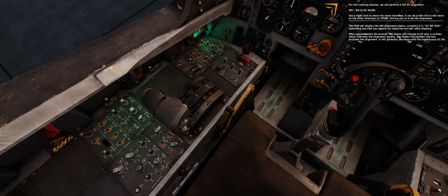To ease the numeric inputs, you may want to bind the numeric keypad of the UFCP to the numeric pad of your keyboard, in the way shown in the figure. Once the full correct latitude has been typed onto the scratch pad, enter it by pressing the highlighted button. In the same way, we will now input the longitude. First press Shift 4 to enter W for west, then continue with the numeric part of the longitude, 1, 1, 6, 4, 6, 0, 2, 0, 1. One or 2 leading zeros must be included if the longitude degrees are less than 3 digits.